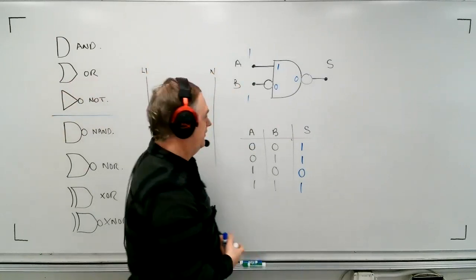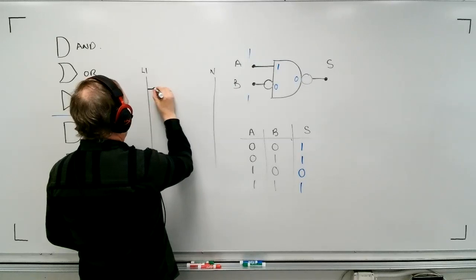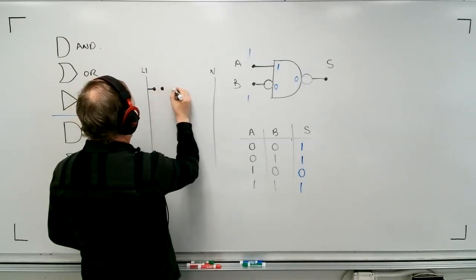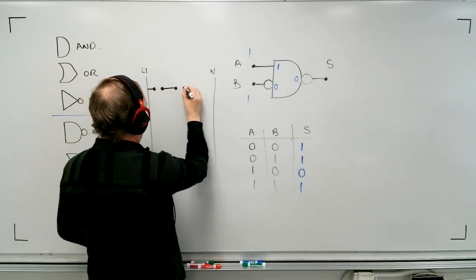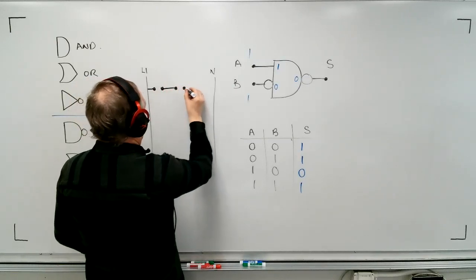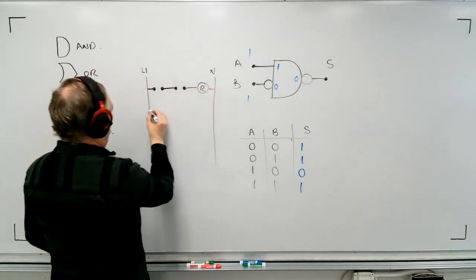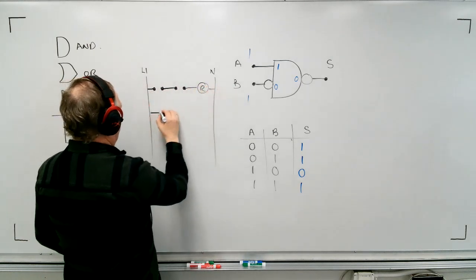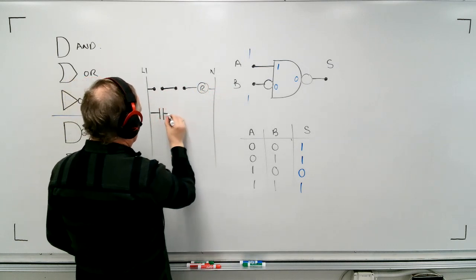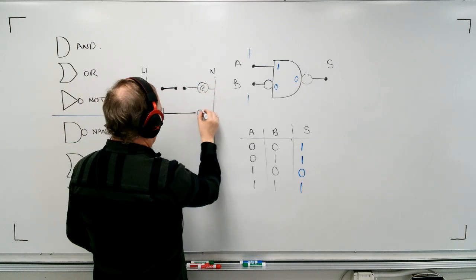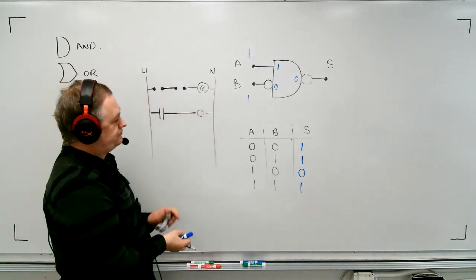And so I know that the first thing I need to do is put two switches, two buttons in series with each other, but don't put a contact on them yet, okay? Don't put a contact. And then this is going to come to a relay like that. And then I'm going to have some kind of a contact here. I'm going to put the normally open because it's easy to change to a closed, and I'm going to show the output. Now, what I have is this.